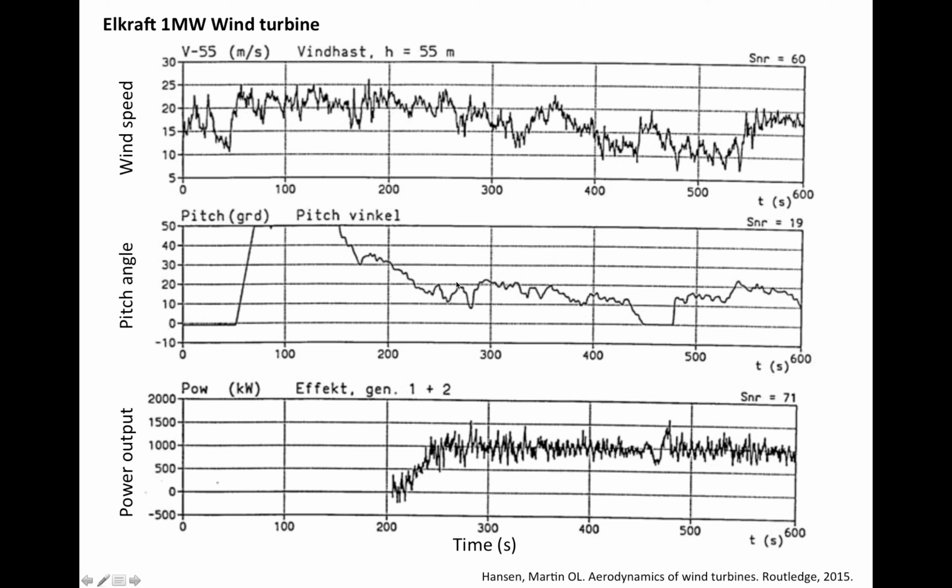As a result, the control system is very often caught out with the blades in the wrong position, because the wind speed changes very rapidly but the pitch angle adjustment process is slow.